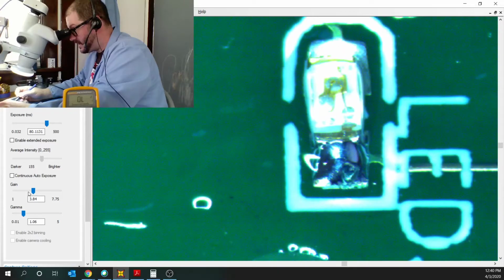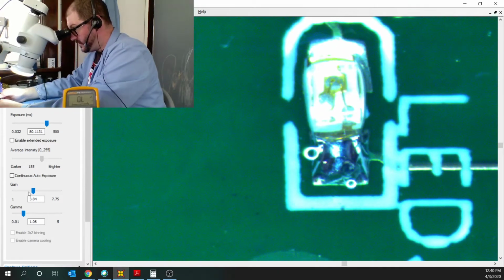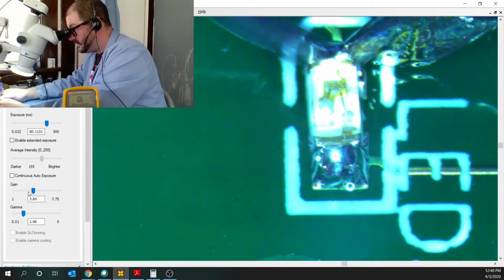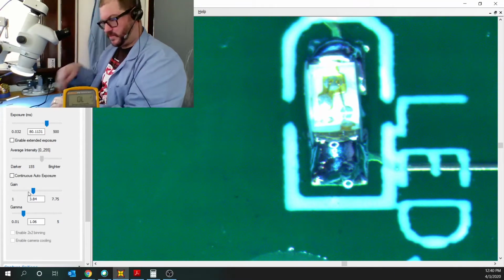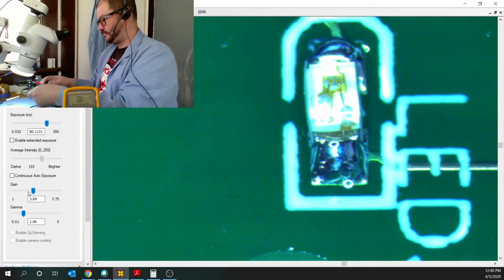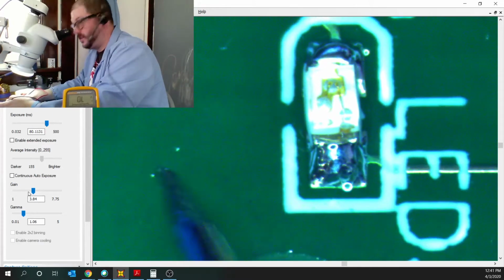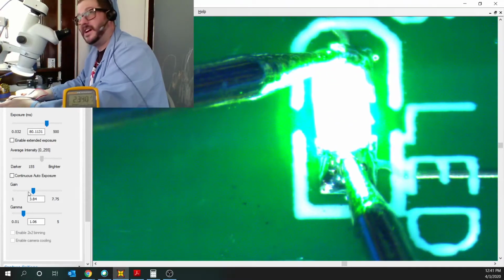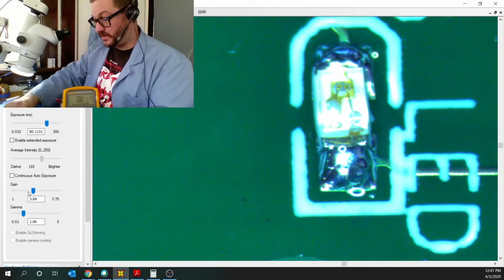I'll stick that guy, put him into place there. That's nice. That all flowed very nicely down. And I'm going to take this other one, put it right here. There we go. Attach that, and now we'll do a final test for the green LED to make sure that he's in the correct orientation. The red probe is here on my right hand side, and the green probe is there, and voila, I get a nice green color LED. Those are all in the correct orientation.